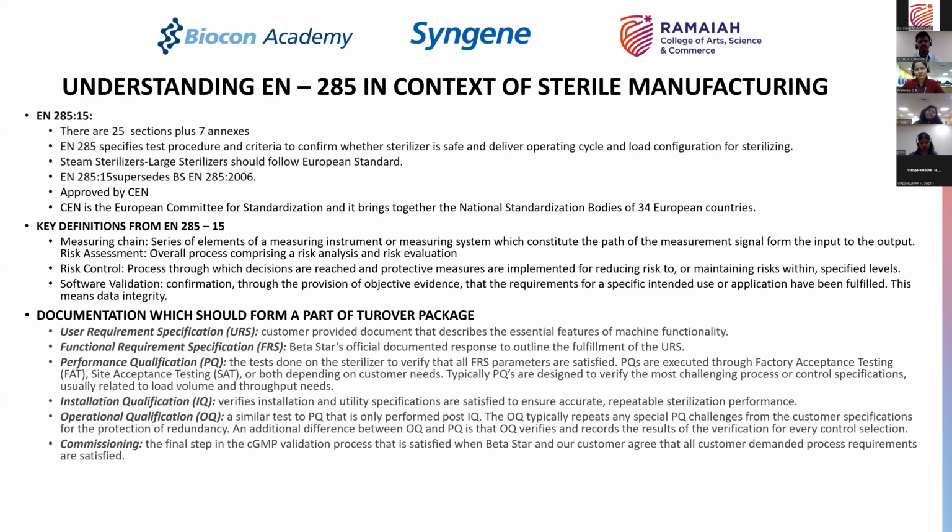Cycle development is done in between the OQ, SAT, and the PQ. The cycle development has to be done, and the final operation which you do is a PQ. Sometimes you can change the sequence there, but generally cycle development is done always before PQ. After the performance qualification is done, you go ahead and start using it for manufacturing. So please remember that for any equipment which you get at the site, the qualification timelines have to be taken into account, because that itself can sometimes take easily 2 to 3 months.